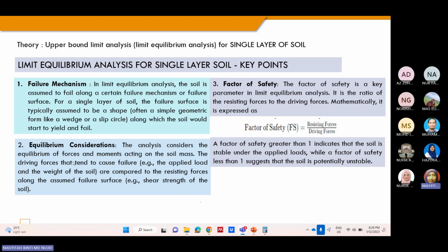So this application can be seen easily kalau you have some kind of the slope problem lah. Sebab bila slope problem, kita ada satu slip circle, satu force adalah shear strength, the other force is shear stress. So these two forces dia dalam keadaan equilibrium. Satu dia try resist, satu lagi dia try melawan. So kalau kata resistant force tu kecil, automatically slope failure akan berlaku. Tapi kalau kata resistant force besar, disturbing force tu kecil, so failure tu takkan berlaku lah. So the same concept applies for bearing capacity lah.